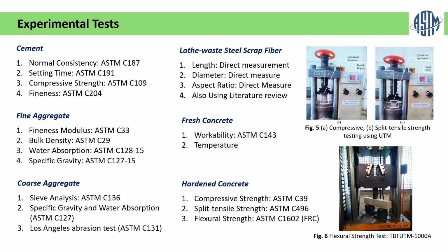This slide summarizes all the ASTM standards that will be followed. For cement, I will perform consistency, setting time, fineness, and compressive strength tests. For fine and coarse aggregate, I will measure fineness modulus, specific gravity, water absorption, bulk density, and abrasion resistance.